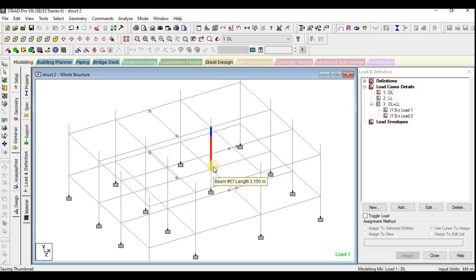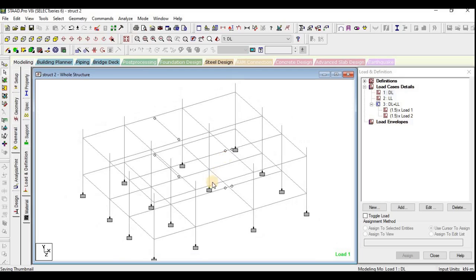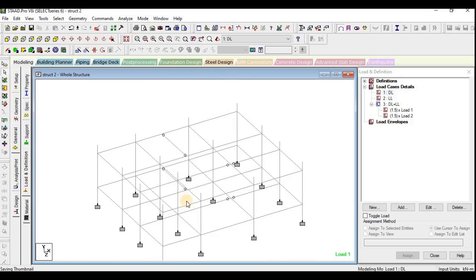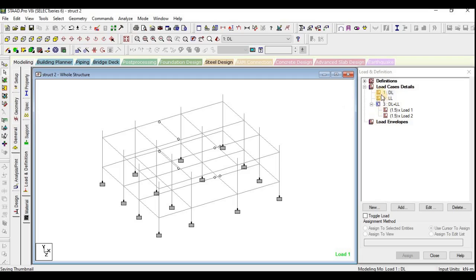This is the concept we are going to consider here. Don't model the slab with the framed structure. If you do, there will be errors in the results. That is not in STAAD Pro, but when you design it, I think it is a fatal error in the design. Now, for dead load, I shall consider only the self weight.